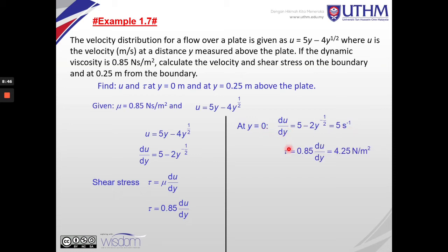Okay, so the shear stress here, we get 4.25. Then at y is 0.25 meter, we get the du over dy, so we get this, 1 per second. So we get the shear stress as 0.85 here.